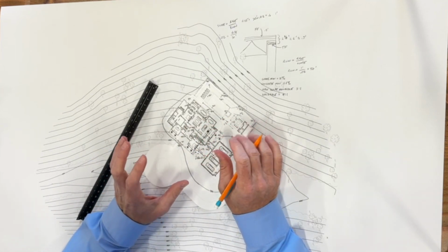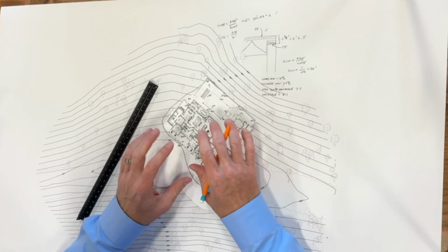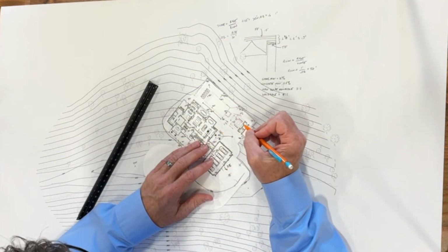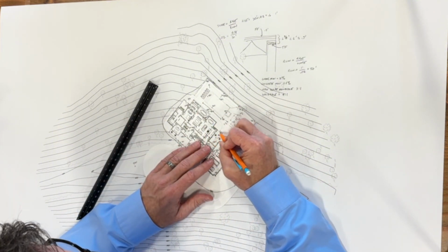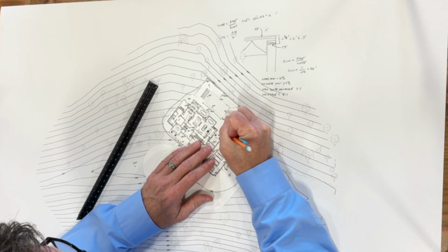Okay. Now in commercial projects, by the way, you got to get down to much more detail, like inches. Here we're just going like 6-inch increments because it's just not as critical. But in commercial, because of ADA and things like that, it's got to be spot on. Okay, so you're actually at 941 right there. So it's going to slope 2% to that edge. And that means that'll be a 941 as well. We'll just keep it single sloping.